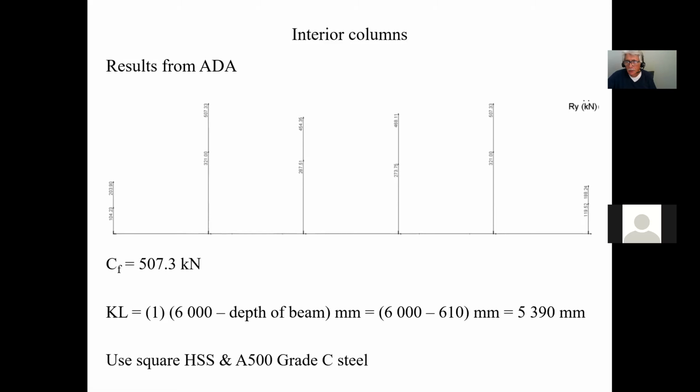Sir, I have a quick question. Yeah, go ahead. The 600 minus 610, that's for everyone, right? Regardless of what beam you have? Well, the beams was a 610 by, I don't remember, was it a 610 by 92 and a 610 by... Yeah, it was. So it's 610. In other words, the drop in is smaller, but the columns aren't sitting on the drop in. The columns are sitting underneath the girder here, right?